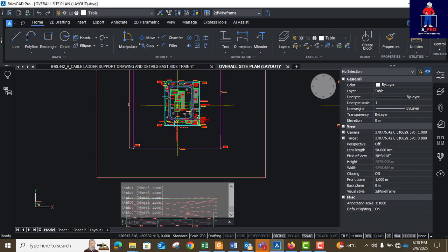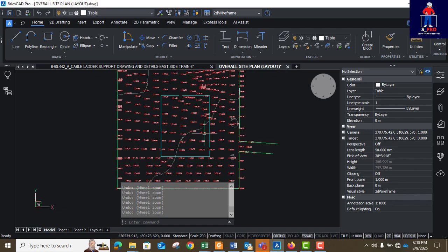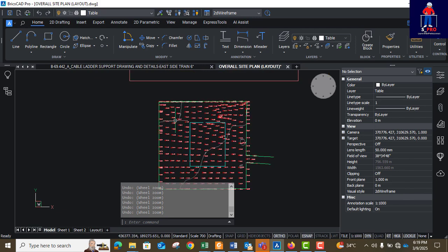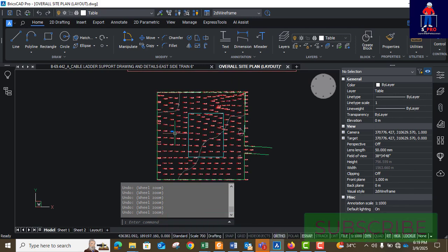Before we start our plot plan, the number one information we'll be needing is what is called the topographical survey drawing. But if the topographical drawing is not available, you can still be doing something if you know the size of the plot. If the client can tell you the size of the plot, you can start doing something from that. But what will validate the size is the topographical drawing.